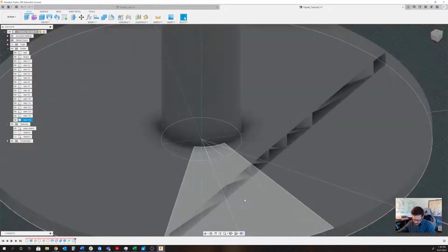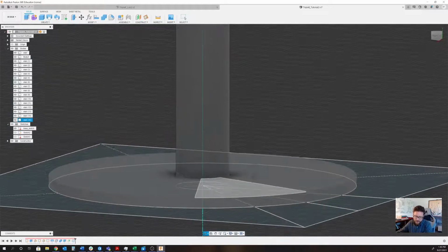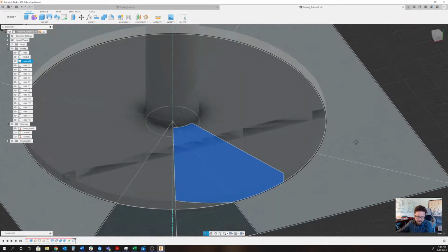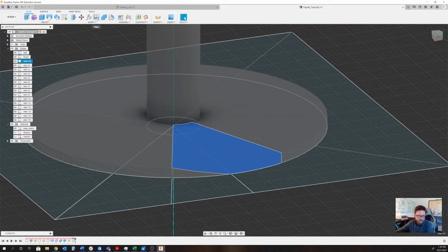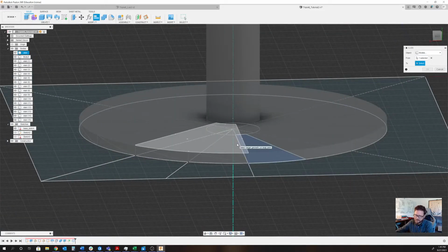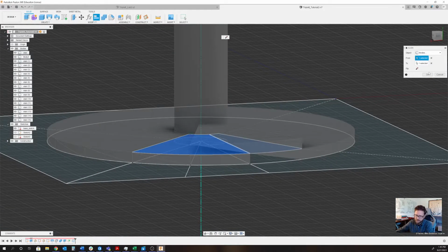But of course, they're not going up as they go. So what I want to do really quickly here, and you can maybe press fast forward if you like, I'm going to take the first stair that's marked as stair number 1, and I'm going to align it. That basically means to make things flush with each other. I'm going to click the align tool, and I'm going to say I want the bottom of this to be the same place as the top of that. And that's going to push this one piece up. And I'm going to hit OK.